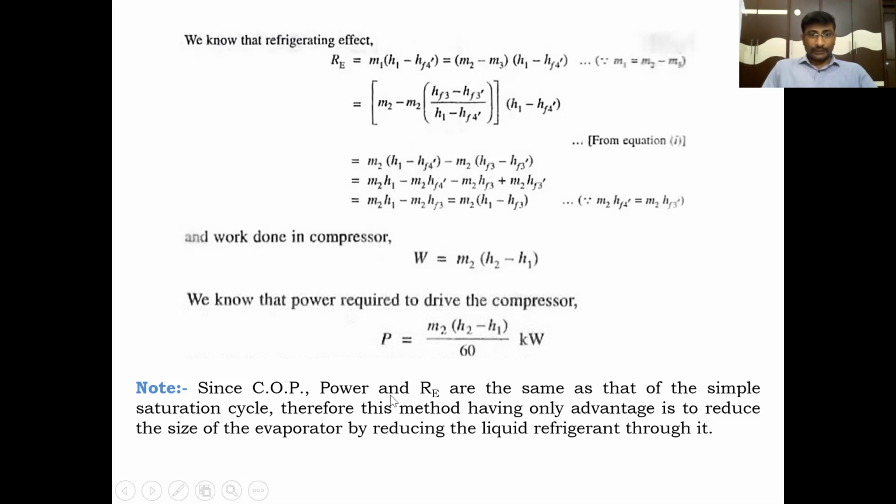So since COP, power and refrigeration effect are the same as those of the simple saturation cycle, this method has only one advantage: to reduce the size of the evaporator by reducing the liquid refrigerant passing through it.